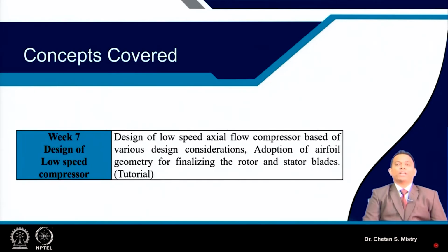And I am sure you might have done your pen and paper calculation, and developed your own Excel design sheet based on what we have discussed up till now. We also discussed the kinds of aerofoils we have used, how to develop those aerofoils, how to stack them, and then how to incorporate the stagger angle in order to make the blades. That will give you the confidence for design of a low speed axial flow compressor.